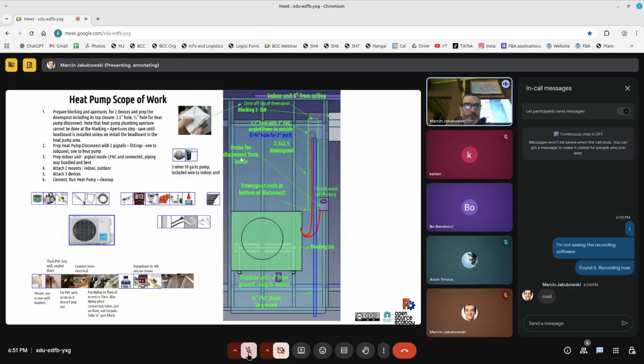Fast wiring is cool. So we do heat pumps. In this build, I would like to try this thing here. There's one wall module that has the heat pump, but the trouble was there's the exterior unit on the outside wall and the interior unit in the house. This time around, we're going to try to fit them one above the other, so we can literally do one modular panel that we build in a controlled environment and just put into the wall. How about that? We have the disconnect in there. We have an outlet for an exterior outlet as well. Might as well do that since we have power there.